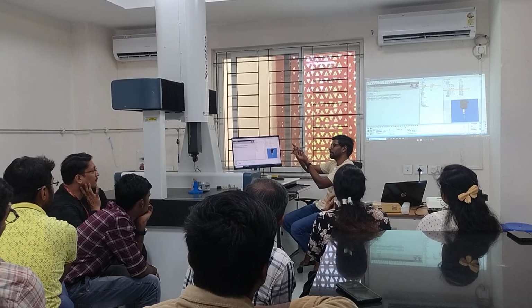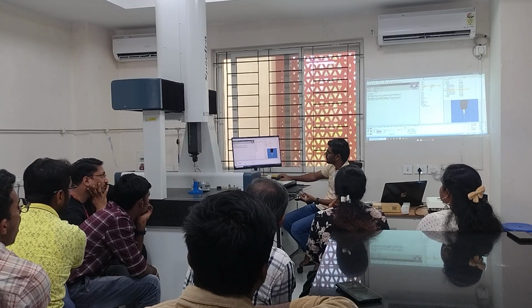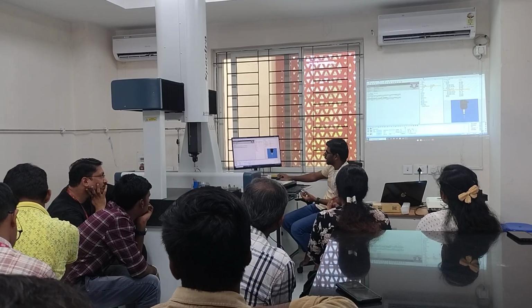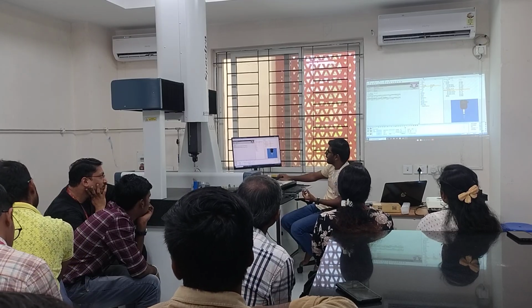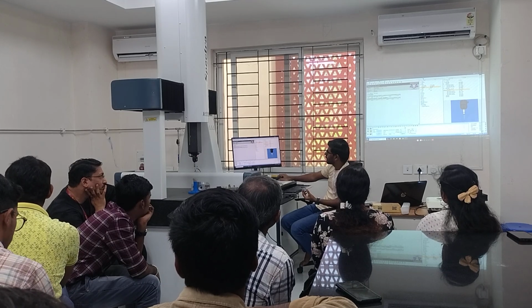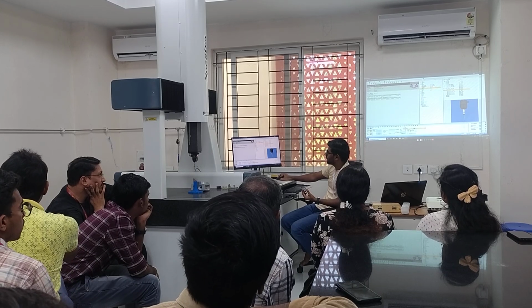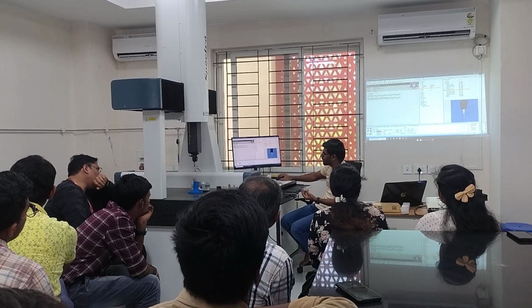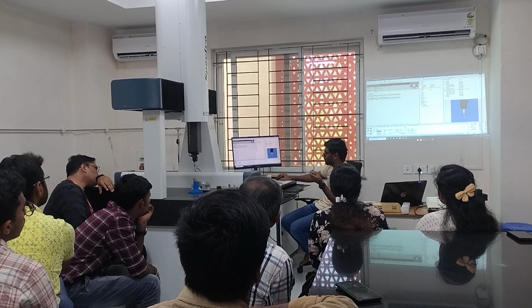Again, I'll try to find the distance between the two planes. I'll go to distance. Again for distance, we need two features. I'll go to the right plane and drag it here. Then I'll take plane 1 and drag it here. So for distance, I think I have given 40.